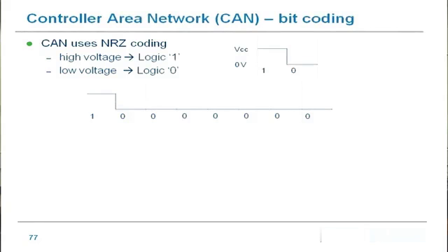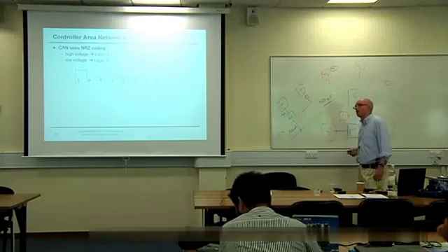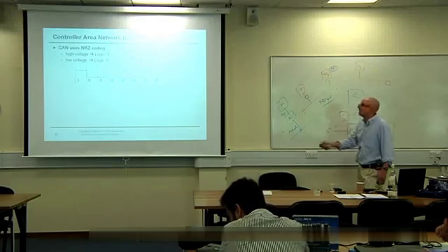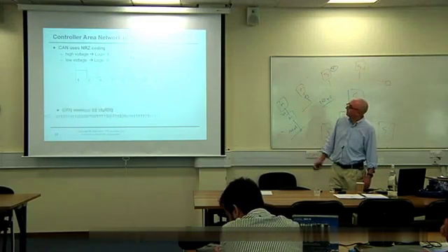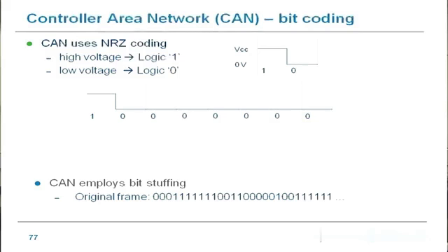If you use any network in these kinds of systems, you need to be aware of what's happening at the lowest level in the system. CAN uses non-return to zero coding. Why on earth do you care? You care because it implies bit stuffing. So at the lowest level, we're not talking the shared clock level, we're not talking the level that we are working with.